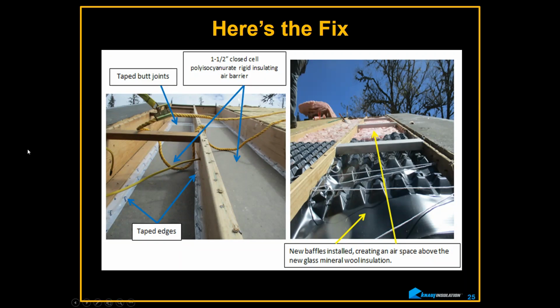So what we did was polyiso because we couldn't get at it from the bottom. I would have preferred to tape it from the bottom where the pressure pushes the tape into itself rather than the pressure trying to lift it from the underside. But this is all we had. There's sealant under it as well. So polyiso goes in. Right below this is nothing more than that tongue and groove sealing that I showed you. And then on top of that goes the insulation.